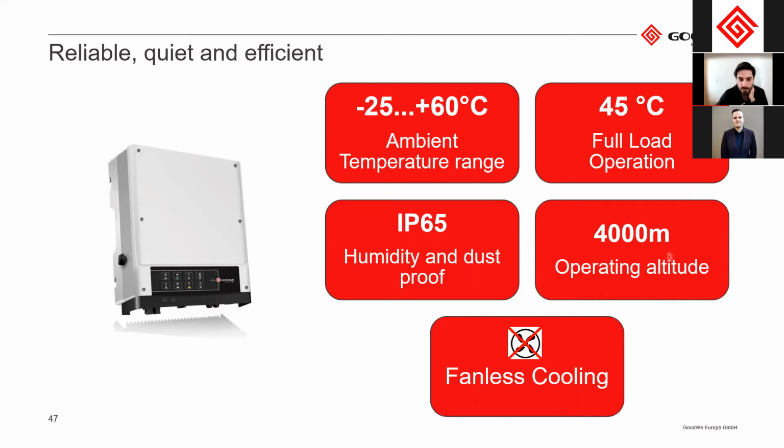This 4,000 meters might not be that important for most of you, in case you don't live at very high altitude. But this also means that the components inside the inverters live up to a much higher safety standard, because at higher altitudes you need to take into account the conductivity of the air, and therefore you need to have better quality components and higher safety standards.